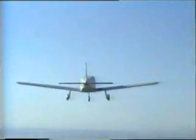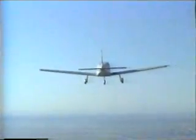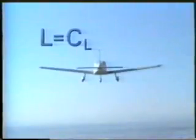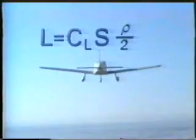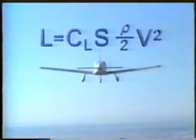To fully understand lift, you must first analyze the various factors which affect it. A simplified form of the lift formula states that lift is a product of the coefficient of lift times the wing area times 1/2 the density of the air times the velocity of the relative wind squared.